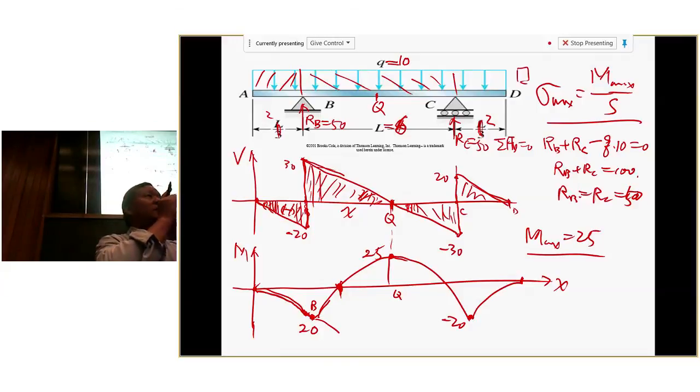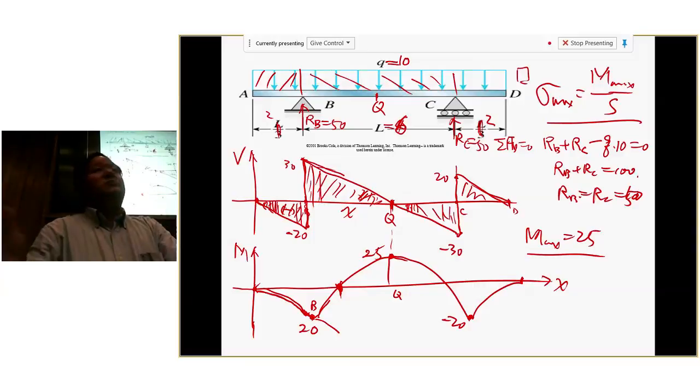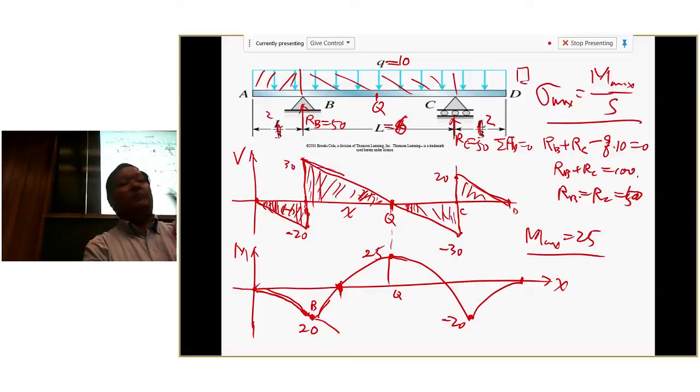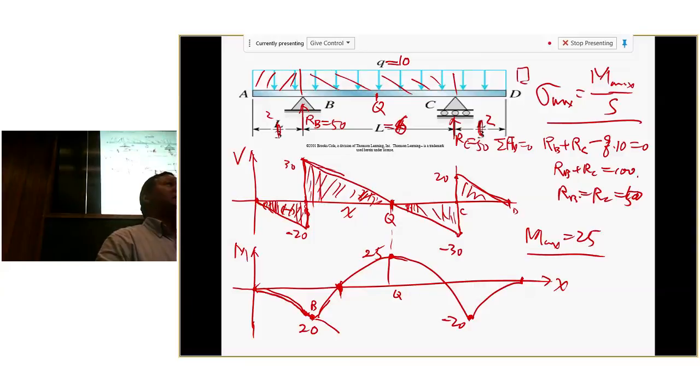What I mean is it will remain straight. So if you look at the slope of the deformed beam, where M is 0 should be straight. At that location, no bending. Okay, you'll see that more when we talk about deformation of the beam. So for now, M equals 0 doesn't mean much. Just say M is 0, no bending, right there. Okay, other questions?